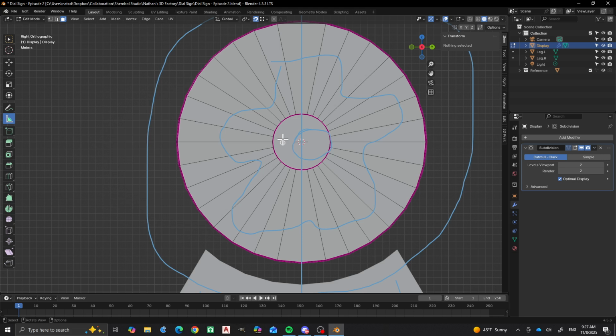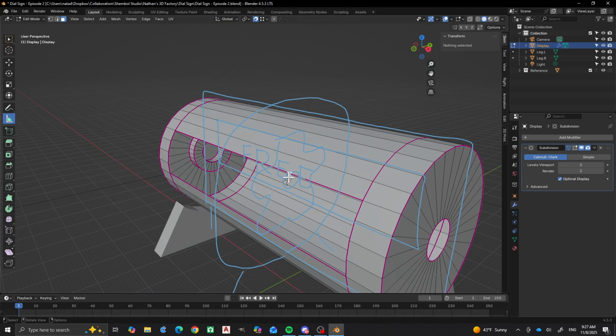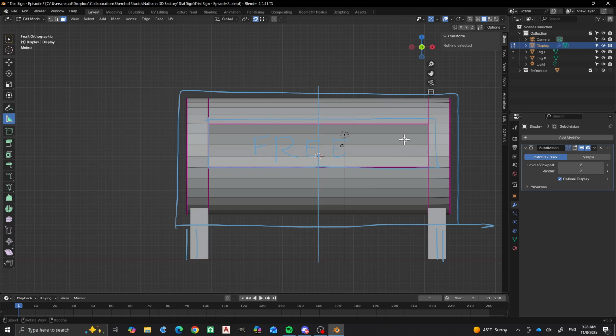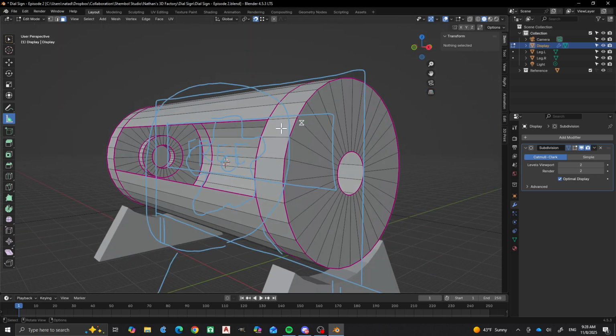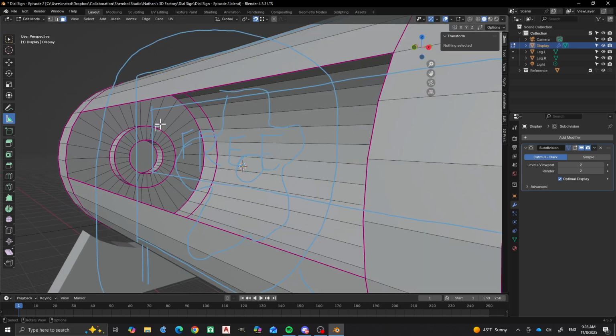So let's X that. If that's 33 for that, I want to have a 30 millimeter drum on this. So that'll give me 1.5 millimeters on each side. I may even do smaller than that, just so that I have plenty of room for it to move. Depending on your printer, there may be varying tolerances on this. Mine gets some pretty good tight tolerances, but I do want to have room for this to move around. So the drum itself is going to have plenty of wiggle room. I think I may actually take this to 28 for the drum size.